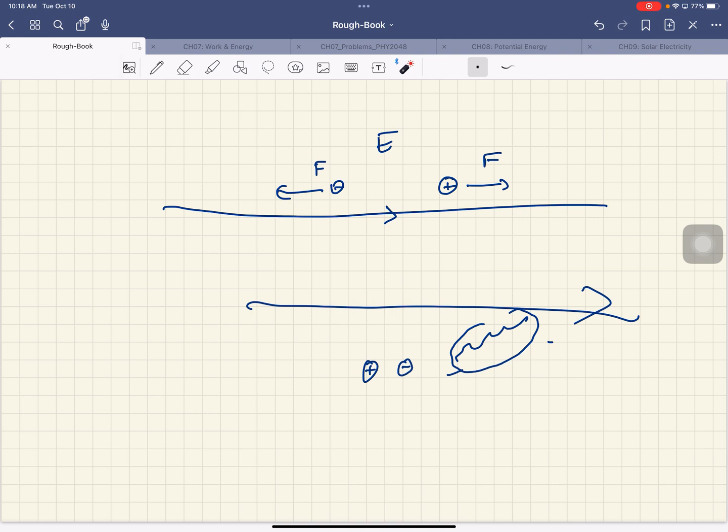And the idea was if you had an electric field, the electric field has a force on positive charges in this direction, in the direction of the electric field. On a negative charge, it's in the opposite direction. So wherever you created this electron hole pair, by absorbing this, if you had an electric field at that location, the positive charge would go in this direction, this would go in that direction, and they'd get separated.